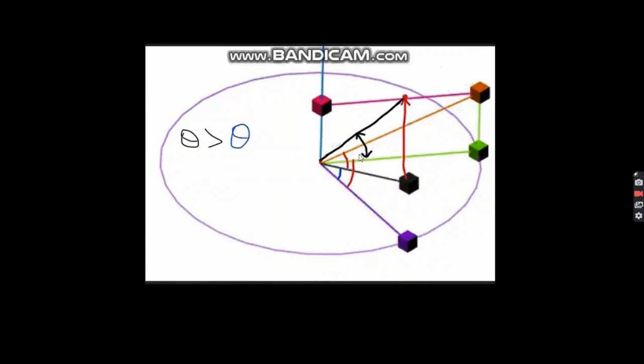Okay, so this is how you can see, if you are rotating the line with respect to this point, then the distance of point B from the horizontal line will remain the same, right? If it is, suppose, 20 mm from this green line, then the projection of the point will be on this horizontal line.